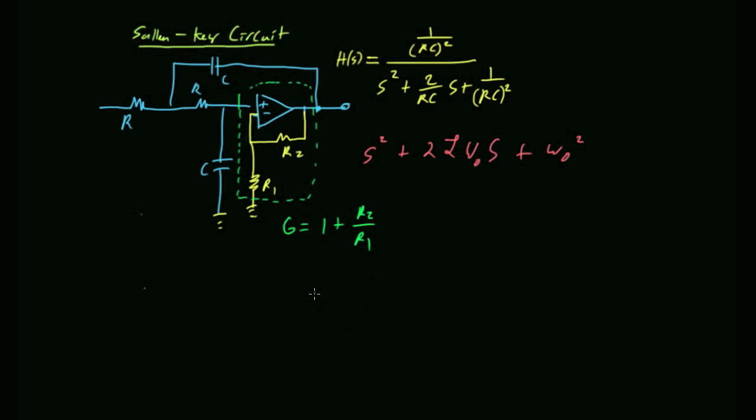Okay, so if you do that, we didn't change the circuit much, right? So you shouldn't expect the transfer function to change much. It turns out all that changes is you get a gain term upstairs, which is nice. And this 2 turns into a 3 minus gain.